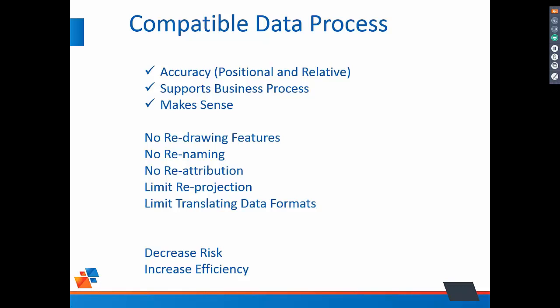So when we bring data into GIS systems, we prefer not to redraw them. We prefer that it gets submitted in a format that is understood from the beginning to, say, be a grid-based format that we convert to a ground-based format, that we then submit in a grid or ground-based format, complete with the documentation to ensure that we have done due diligence along that process and ensure we know what the data sources are that came from GIS, that have been transformed, that are going back to GIS, and what the new features are that we've created and that the standards that we've used to create them are compatible with the end system.